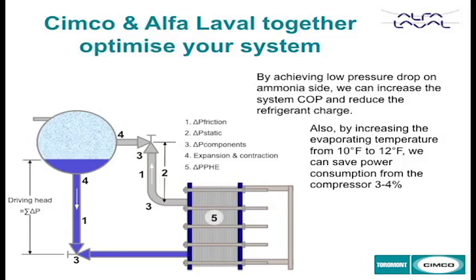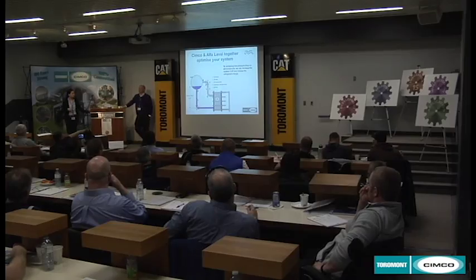This is very important, as I mentioned. Not all the heat exchangers are designed in the same way. So in our partnership with Cimco, we take into account the pressure drop we're creating on the refrigerant side. And by that, we consider, while we are designing the heat exchanger, to maximize the energy efficiency and to lower the power consumption.